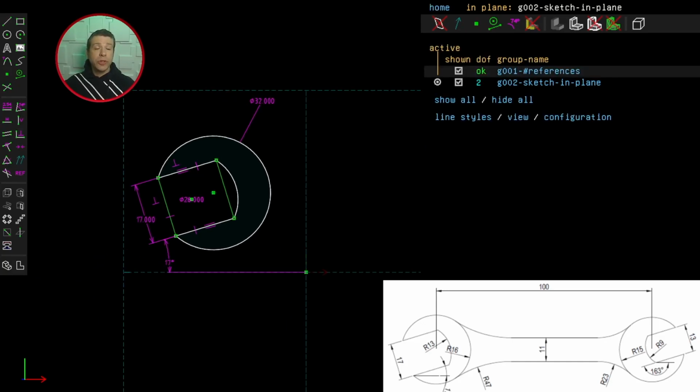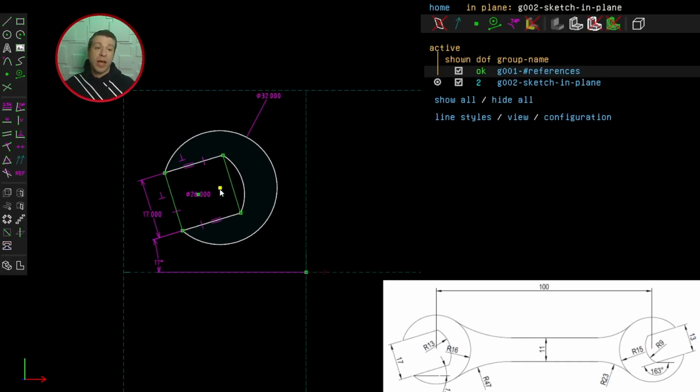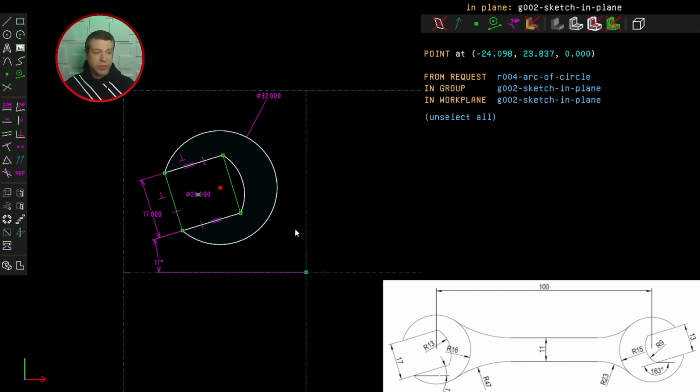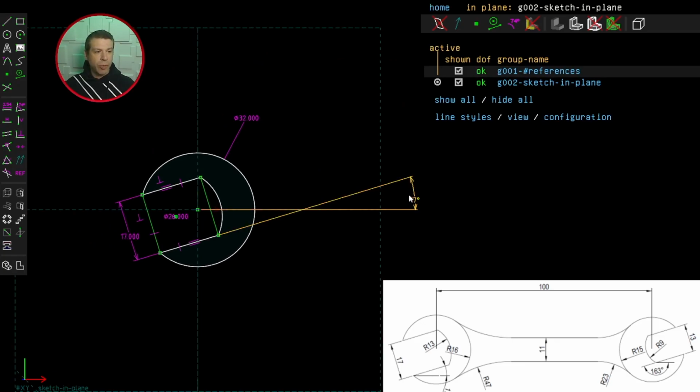And now we've got 2 degrees of freedom, and that's because I can move the sketch in the plane. So let's anchor this sketch. So I'll select the center and the origin and click constrain point on point. And I can tidy this up a bit by dragging this to be here. Okay, so that's one end dealt with.